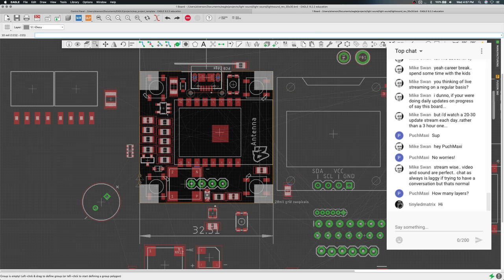I want to stick with 805. I want to make it less than 33 millimeters. And I want it to be two-sided, 2 layers. So this is going to be hard to route without a power plane, but I've done it before. If I have to, I can drop these down to 603, and I can get more traces through there.